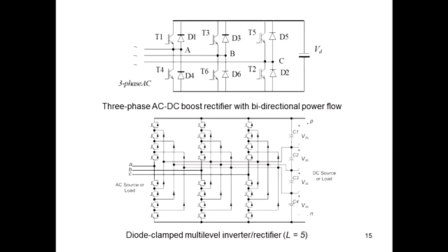If this is the input, we can produce an output at the same time making sure that the currents are sinusoidal and in phase with the AC supply, which is the output of the wind turbine generator. Okay? And if a DC supply is available from the solar or from the wind turbine, we can then connect to the grid by using a regular 2-level inverter. All right.